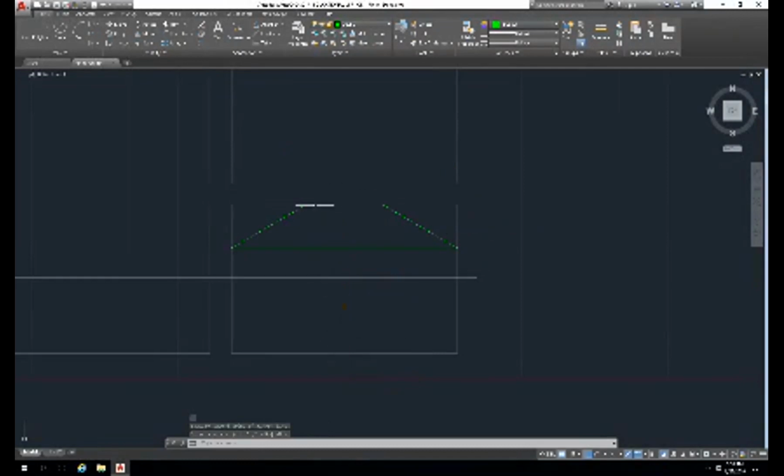See, the thing is that we're not given this distance on the drawing. So we had to draw lines to figure this out. So let's do trim and say this line and this line. Press enter. Should let me delete this piece and this piece. Oh, okay, I can delete this piece too. Okay, good. This piece, this piece. What about this one? This one too. Perfect. This one and this one. Perfect. Okay, press enter.